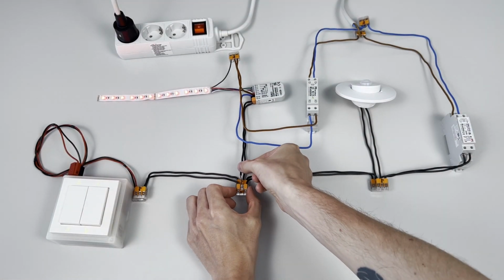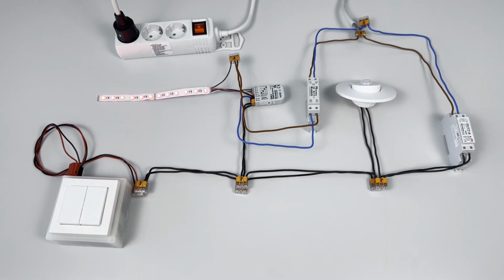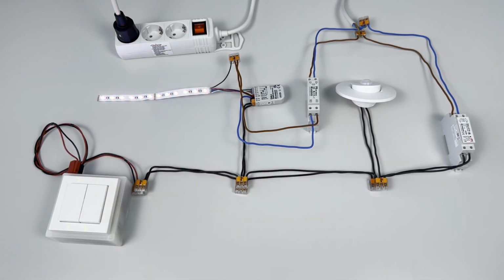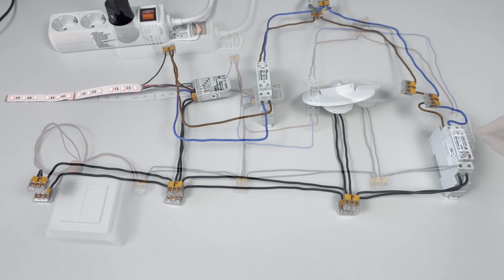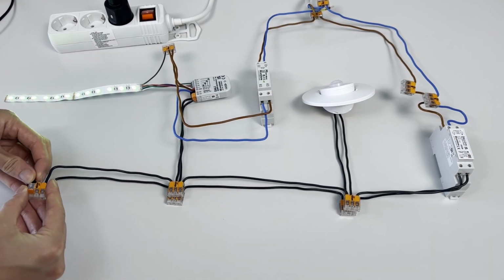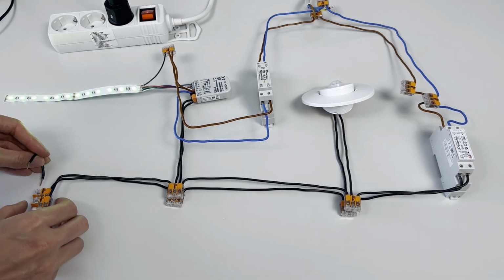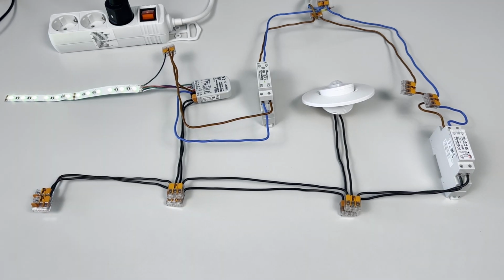To resolve errors related to a disconnected or short-circuited DALI line, reconnect loose or disconnected wires. Use the test button on the DALI power supply to identify devices that do not respond. These are likely not properly connected to the DALI bus. Locate and fix any short circuits. To isolate the short circuit, disconnect sections of the DALI wiring one at a time and observe the LED on the DALI power supply. When the LED stops flashing, the shorted section has been found.